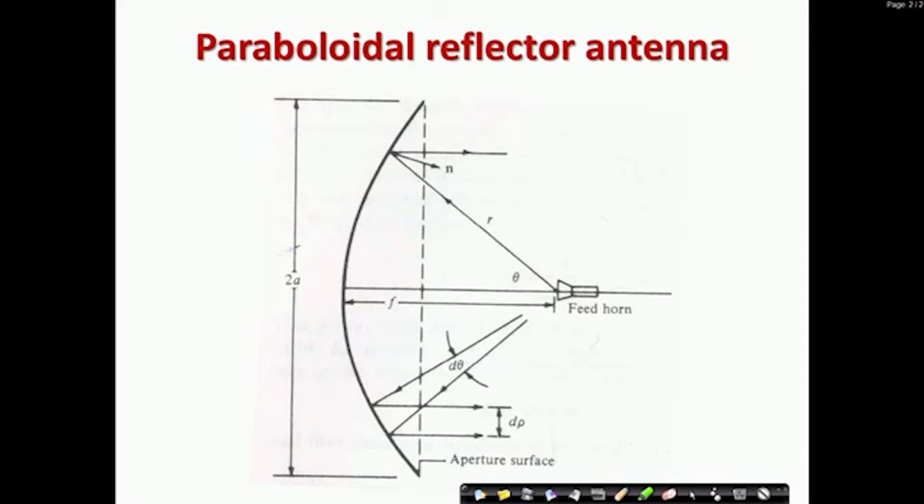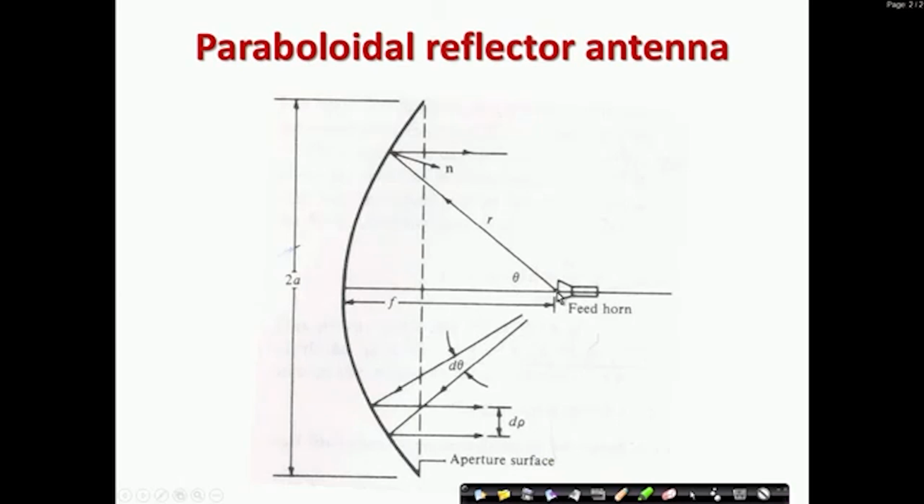So, it will definitely give us very high directivity. If I make this choice, I will get very high directivity, but the efficiencies will kill that directivity. That is why we will see that this is not done. Also, here I will say what the angle is, because though I can make this paraboloid reflector come to pi by 2, we do not do that, because then our aperture becomes very small. So, up to a certain angle it is there.